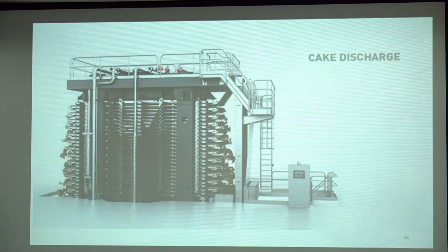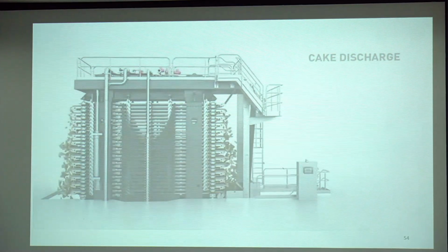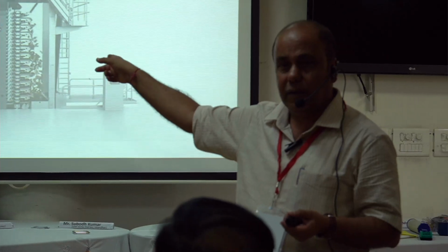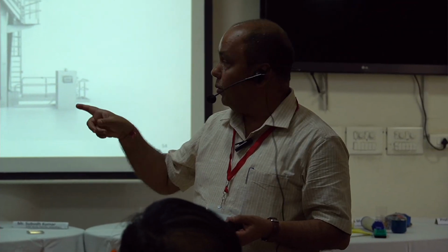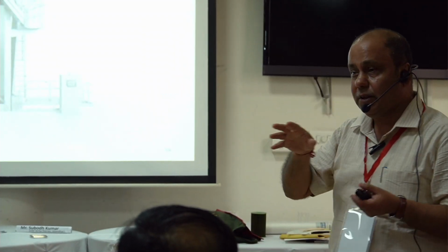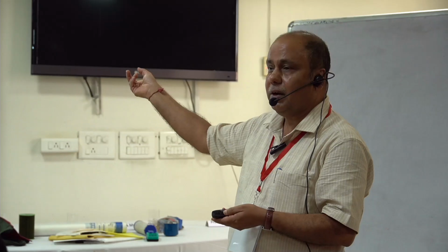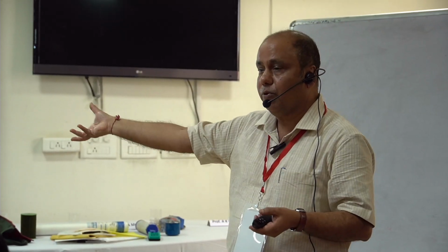So it is basically a batch process. It is not a continuous process. Like the drum filter, if you see, it is a continuous process. Continuously. Like the disk process, it is a continuous process. But here it is a batch process because initially it is pumped inside the chamber, it is compressed, and dry material is coming out as the conveyor is moving.